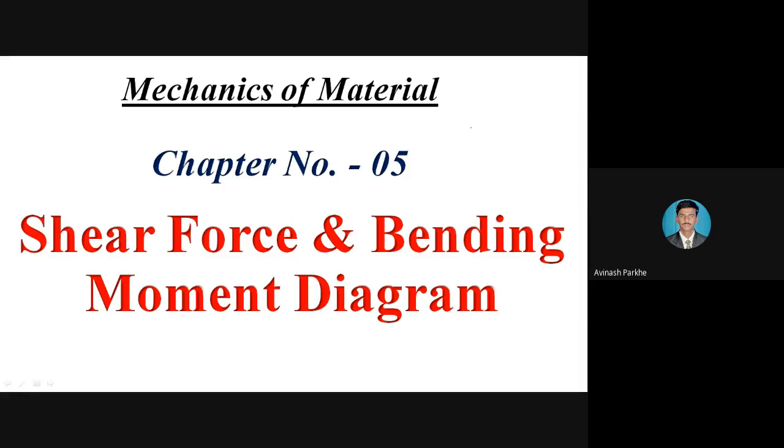That means initially we go for the analytical calculation, and whatever value we have calculated for the shear force and for the bending moment will be converted into a diagram. The diagram drawn from the shear force calculation is called the shear force diagram, or SFD. And the other diagram, drawn using the bending moment calculation, is called the bending moment diagram, or in short the BMD.